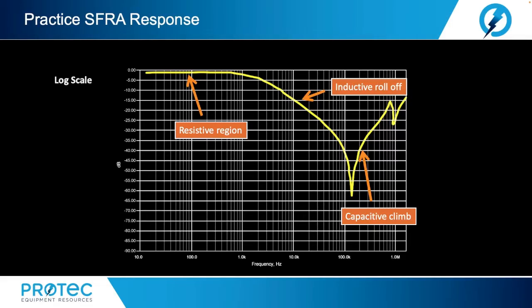At high frequencies around 200 kHz, the inductive roll-off is replaced by a capacitive climb. This is where the capacitance between the coils of the specimen counteracts the effects of the inductive element. There is another effect in the coil around 1 MHz. This may relate to its construction in layers where mutual inductance and capacitance between layers begin to have an effect.